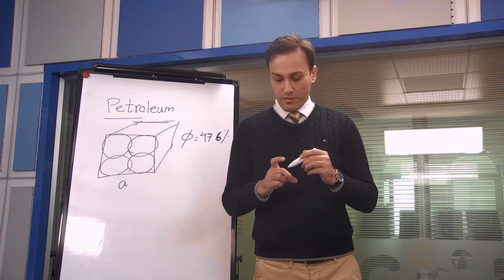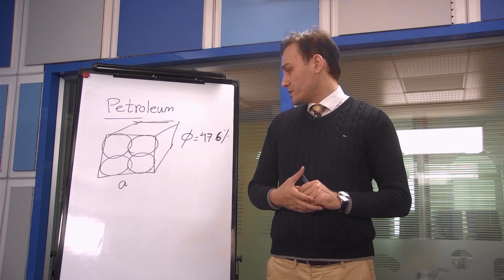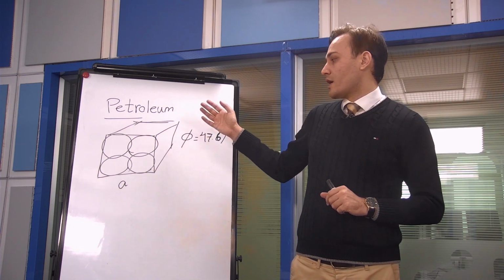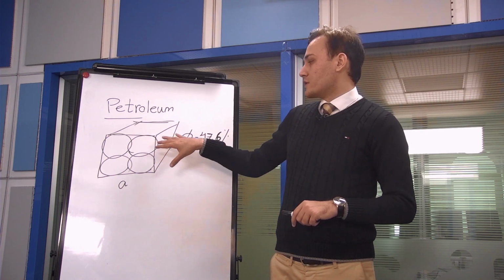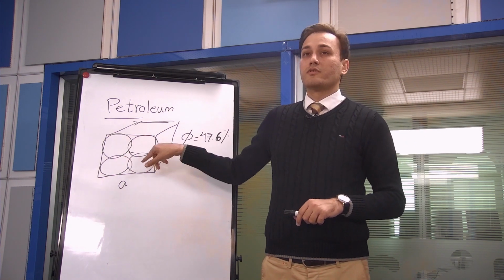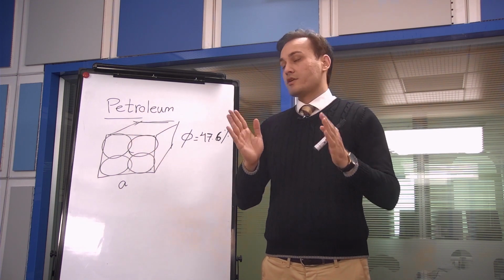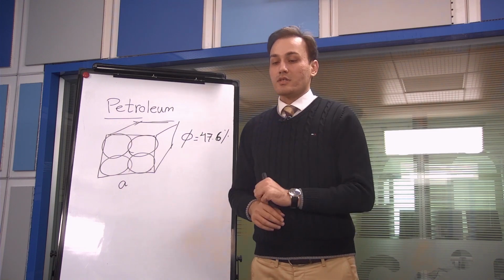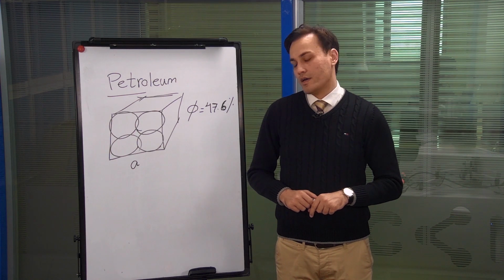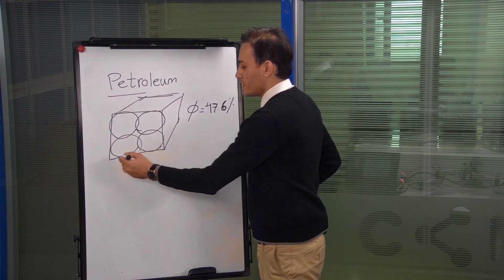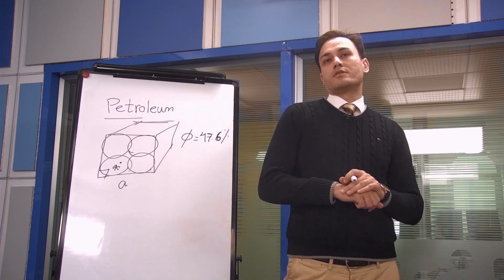In reality, the porosity can change in values between 3% to 40%. So this is a very idealistic approach for the value of the porosity, because in reality we have different sizes of grains, and also the packing may not be like this, and there can be some kind of angles. As you can see here in the second figure down there, there can be some other angle than this 90-degree here, and that will create other types of packing.